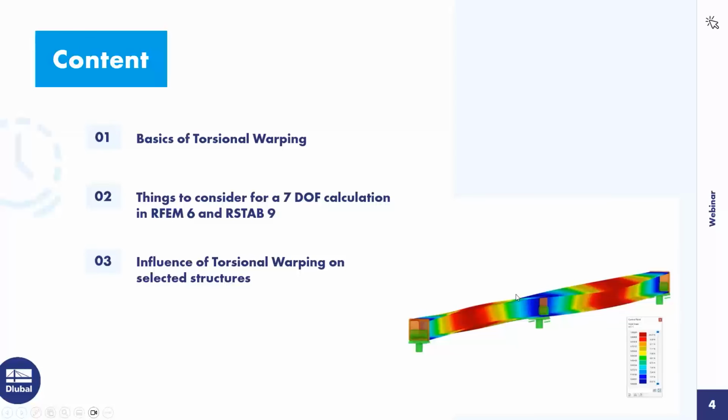So in fact, most steel profiles are optimized for bending rather than transferring torsional load and are particularly affected by warping torsion. So we will mainly focus today on steel profiles and on steel sections. I will maybe lose some words also on solid sections, but this will not be the focus of this webinar.